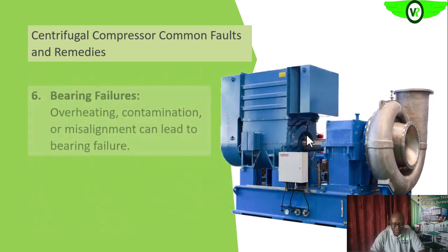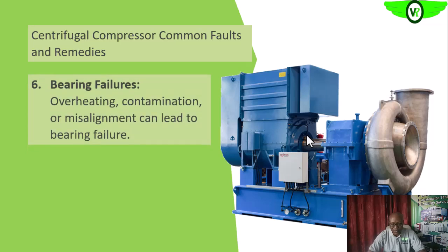So, still on faults and remedies, bearing problems. Remember the overheating that we talked about the other time can actually heat up the bearing and damage the bearing. Then misalignment between the driver, the gearbox, and even the compressor itself can lead to bearing failure. And for us to observe this, once the bearing starts failing, vibration will definitely increase. So we can also carry out vibration measurement and analysis to tell us when the bearing is failing.